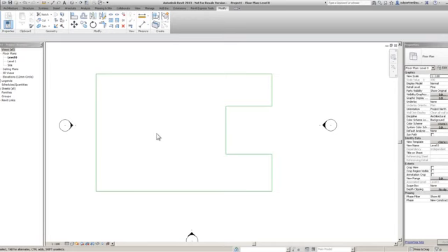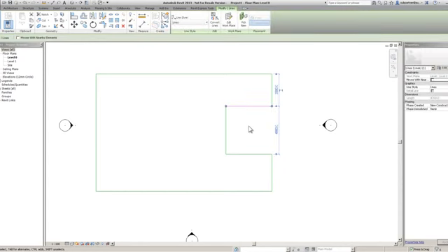Now once we've done that, I'm going to start to introduce you to constraints. Just a couple of little constraints that we have inside Revit. Now I'm going to left click that line just there. And just like when we had a rectangle and we picked a line on the edge and it gave us our temporary dimension, giving you the setting out from another line, it's doing the same here. But because we've got lines either side of this one, it's giving you the setting out in both directions. Now I can quite simply, if I pick that and go 3 meters, you can see the line will move to accommodate that new input, and this one here will update.